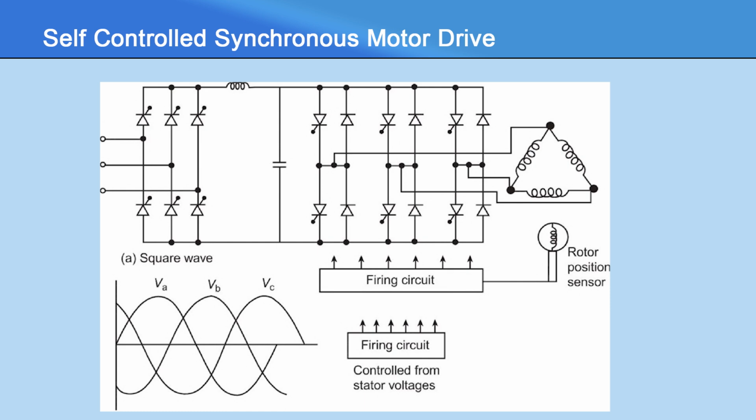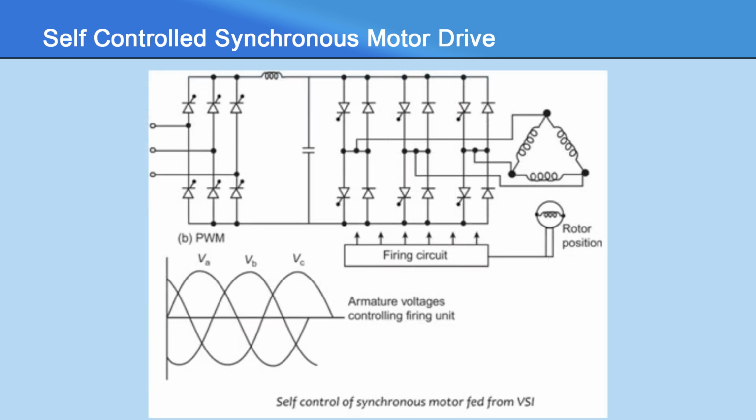The speed of synchronous motor can be varied by supply frequency variation similar to an induction motor. The applied voltage must be varied in this case also to have maximum torque capability and to avoid saturation at all frequencies. A synchronous motor can receive its variable voltage, variable frequency supply from a cycloconverter or a DC link converter.